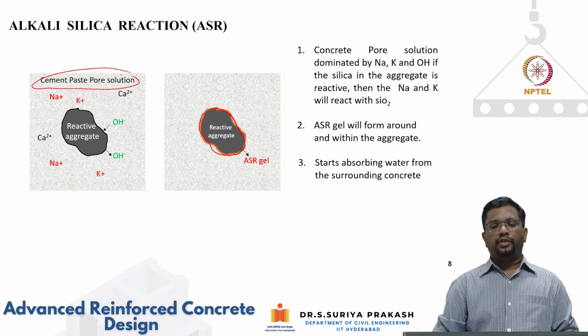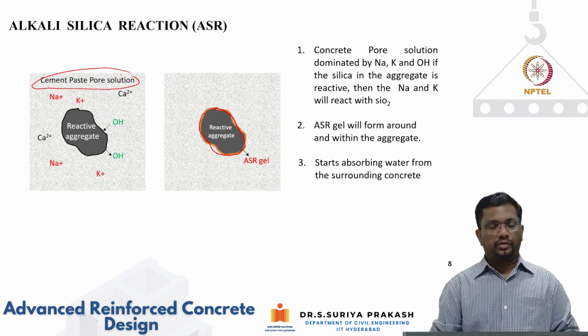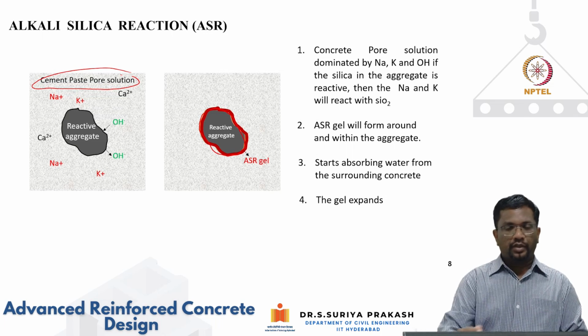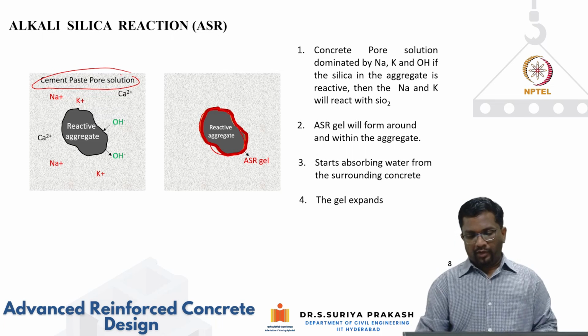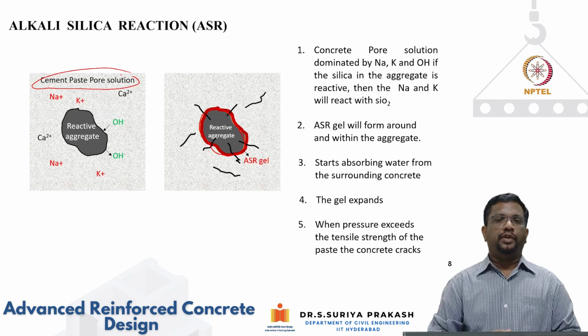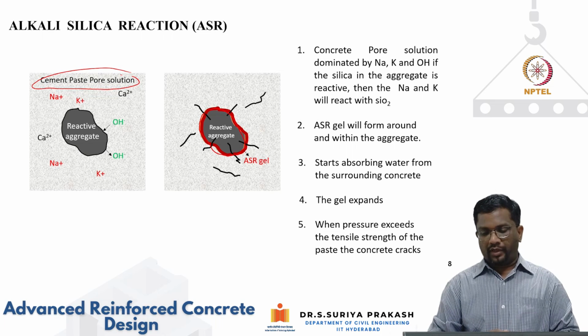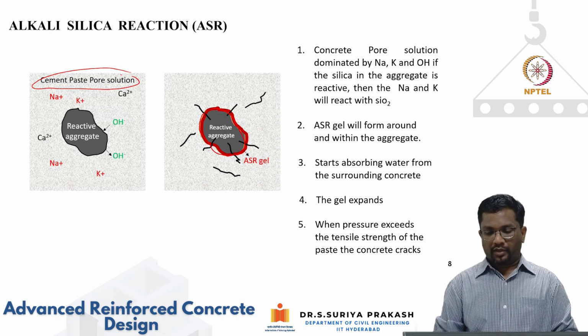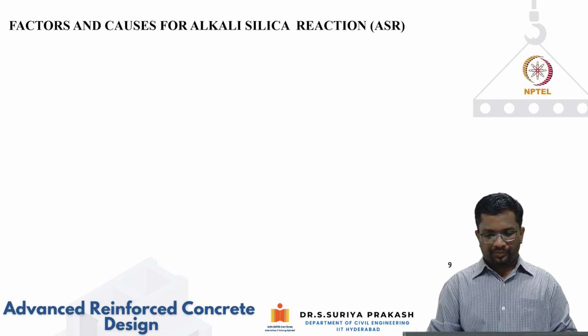Now this gel will start absorbing moisture from the surrounding concrete, and then the gel will start expanding. So you can see that the gel has expanded now. When the gel expands, it creates a lot of pressure around the surrounding areas, and the pressure can exceed the tensile strength of the concrete and create a lot of cracks. So this is the mechanism through a very simple illustration.